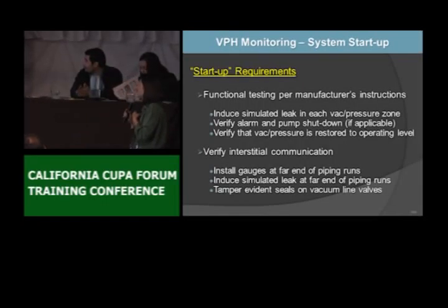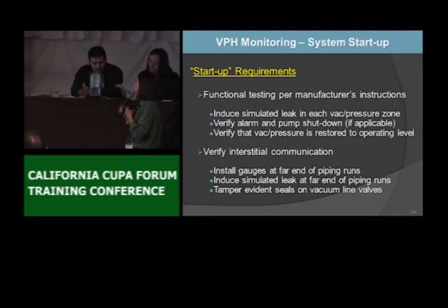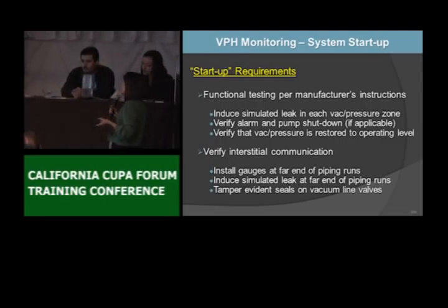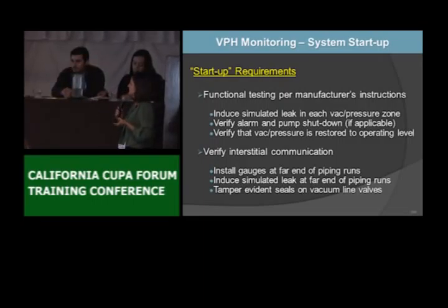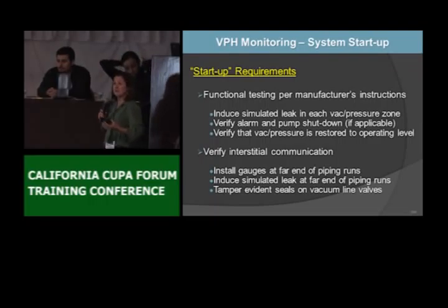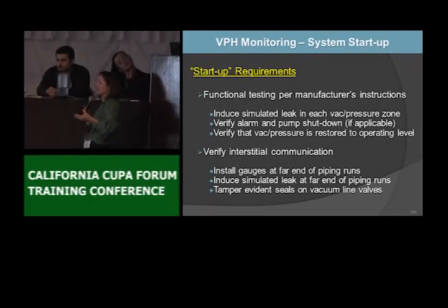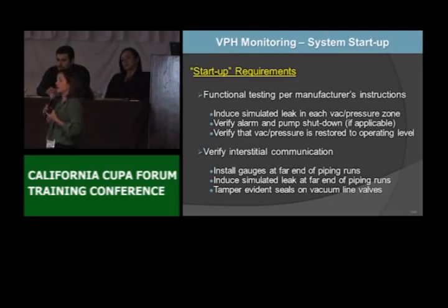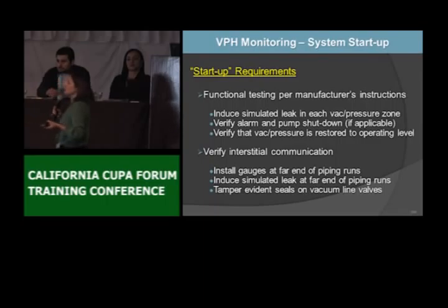Okay, so of course, as with any system, you're going to have startup requirements. And part of it, just like pre-2004, you're going to run through that final inspection, and you're going to do functional testing. So it's nothing too new. You're still going to do functional testing of your typical 208, some sensors, but you're also adding to that. You're doing your functional testing of either your vacuum sensors or your additional hydrostatic sensors, depending on the type of continuous monitoring that you've picked.